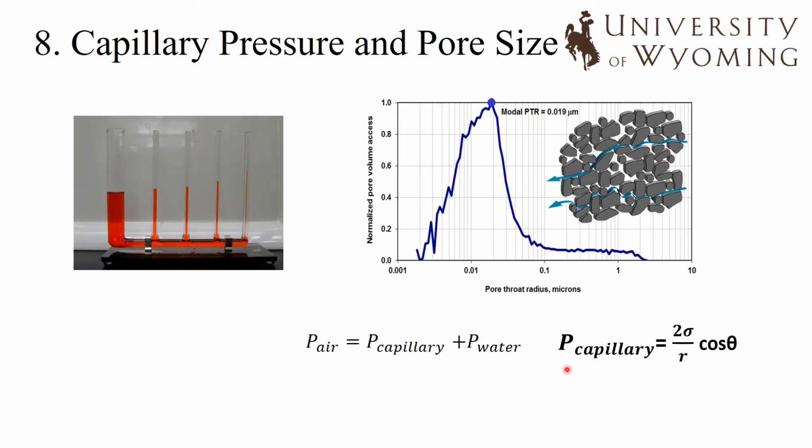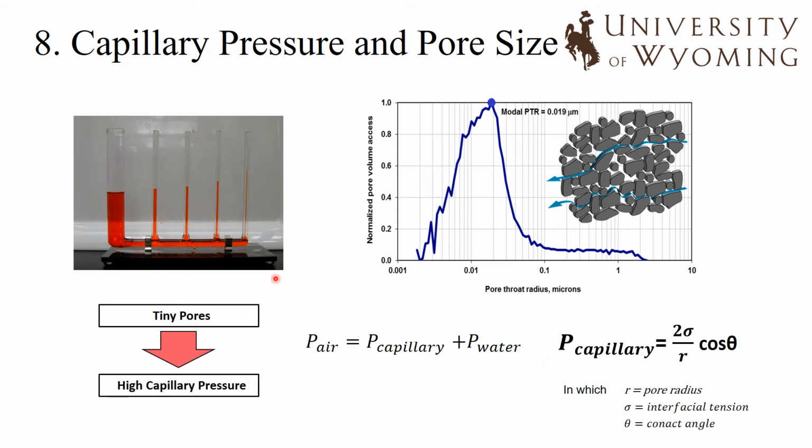So in order to get the capillary pressure, we know that when we have tubes of different sizes, like normal tubes, we can have the water level, or the fluid level, at a certain level, but when it becomes capillary, this level will probably go higher. There are several relationships, or several equations, that describe capillary pressure, but one major one is that capillary pressure is equal to the pressure of the non-wetting phase minus the pressure of the wetting phase.